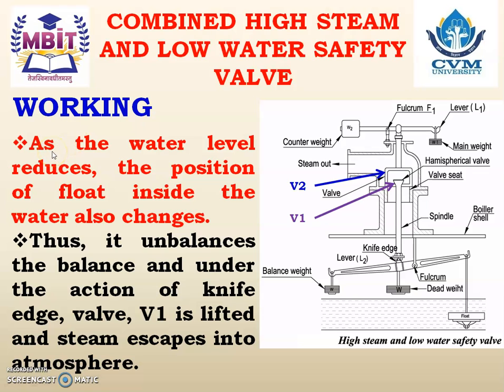Now let us see how it provides safety against low water. As the water level reduces, the position of the float inside the water also changes, and thus it unbalances the balance, and under the action of the knife edge, valve V1 is lifted.